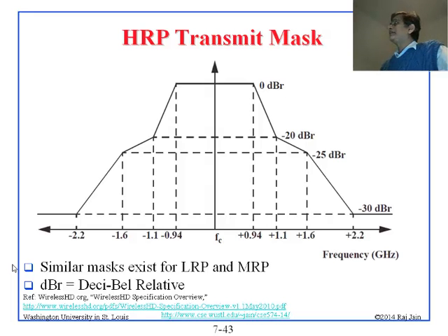So basically the idea is that this is overflow into the next channel. If your channel is 1.76 or something, your channel really ends here. And this is overflow into the next channel. That overflow should not be more than minus 25 dBr. That is the kind of idea, and much of this region is so low in power that it is the guard interval. That's why they keep the guard carriers, which they don't really use. So they are mostly going to use this part here.